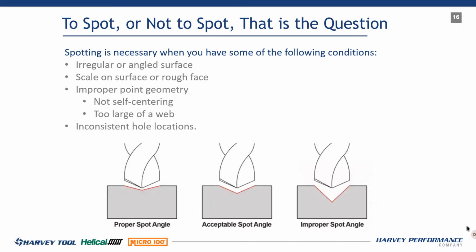Now here's the thing, you're going to see two different carbide drills. Usually some are split, but other ones will have a 4-facet grind on them. I'm going to tell you right now, if you use a 118 drill or a 140-degree drill and it has a 4-facet point, those 4 facets, the 2 facets come on center, that will create an apex and will help self-center. So those drills can self-center.